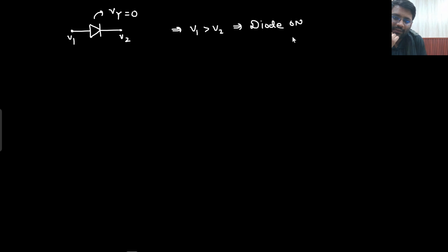here I am saying V1 potential, here I am saying V2 potential, and I am saying that cut-in voltage is 0. Just as I say cut-in voltage is 0, you will be very happy. You will say that sir, if V1 is greater than V2, then diode is on. And sir, if your V1 is less than V2, then sir, diode would be off. Right?